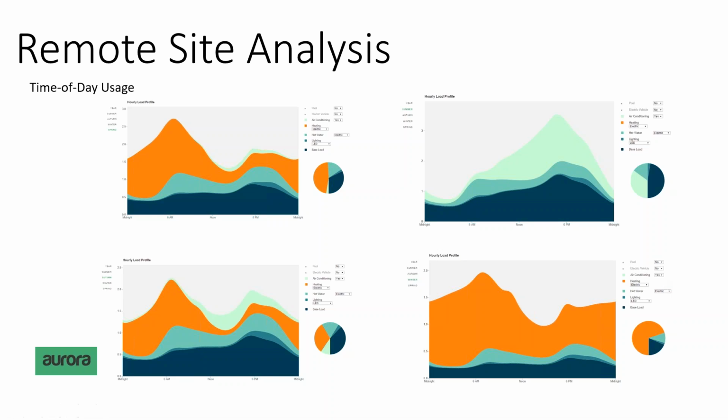It's useful to have interval data. We were talking about this yesterday. On your electric bill, you get the volume under the curve. But what we can see is based on what season it is. Here in Mississippi, we have air conditioning load. Your air conditioning load is going to increase throughout the day and then maybe decrease as temperatures drop at night. Whereas with heating loads, generally you see a high heating load in the morning, and then you're just keeping the building warm throughout the day.